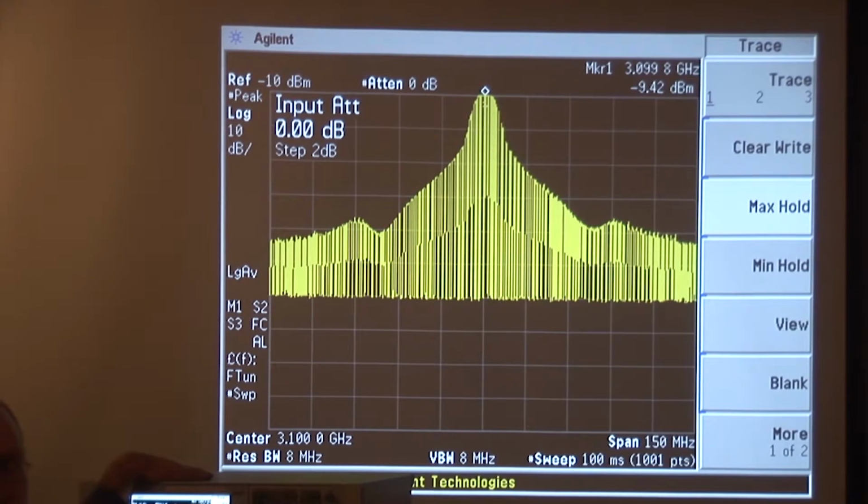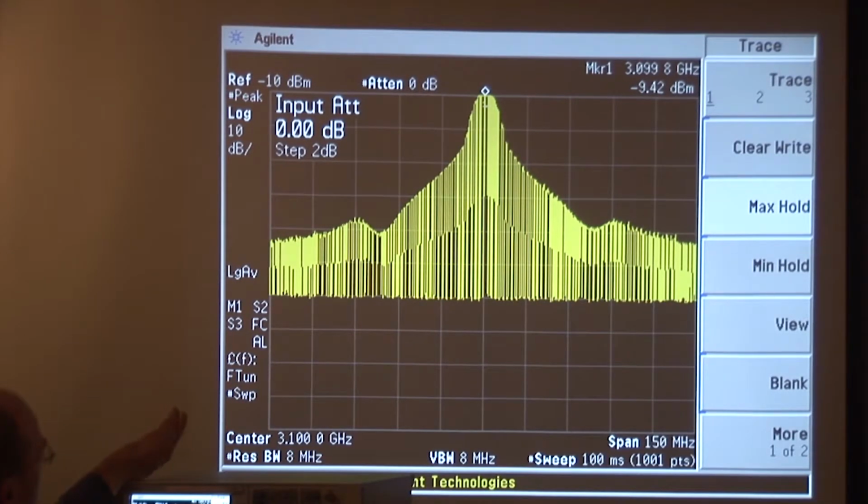And by the way, if you ever have to take a really quick look at a radar, that's not a bad way to do it. You get a good idea here of what it probably more or less looks like. And we do see the dynamic range problem. We've only got about 60 dB or so, maybe, and I could do some here. In fact, I will do some that'll get me about 70 dB of dynamic range, but still it's not really enough.